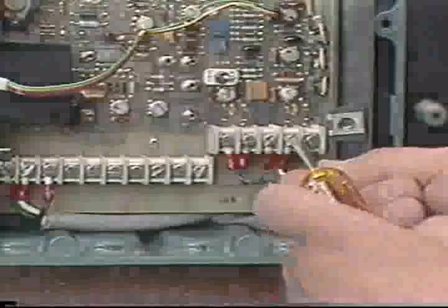As fluid passes through the meter's magnetic field, the fluid acts as a conductor. The change in potential varies directly with the fluid velocity. This voltage is sensed by electrodes in the flow meter's walls. When the flow increases, the magnetic flow meter's output increases. And when the flow decreases, the magnetic flow meter's output also decreases.